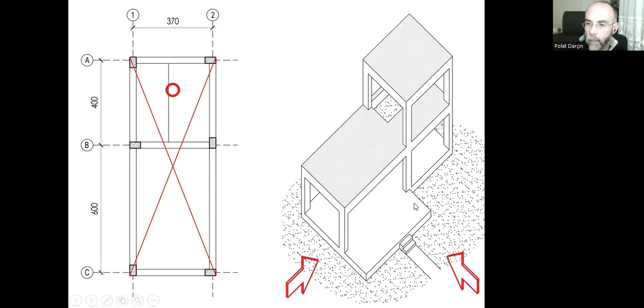But since this part has three floors, the gravitational center has been moved towards the heavier side, and it doesn't want to move. So these beams, these connections will crack, will break down, and it can cause that part of the building, or maybe the whole structure, to collapse down. Once they are broken, they cannot stay in their place, they will fall down.